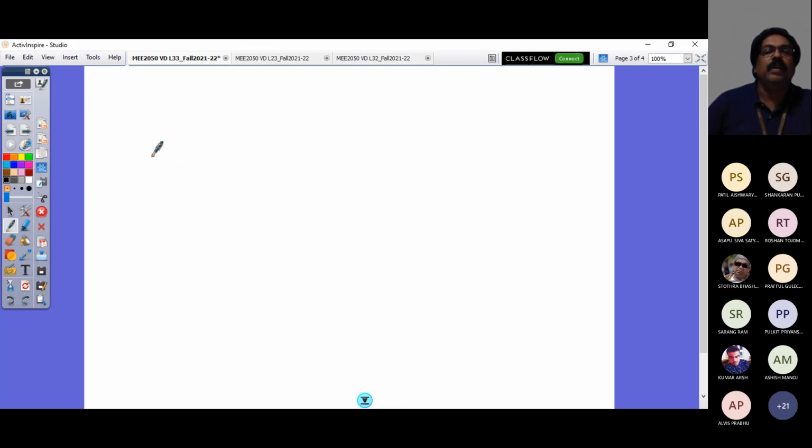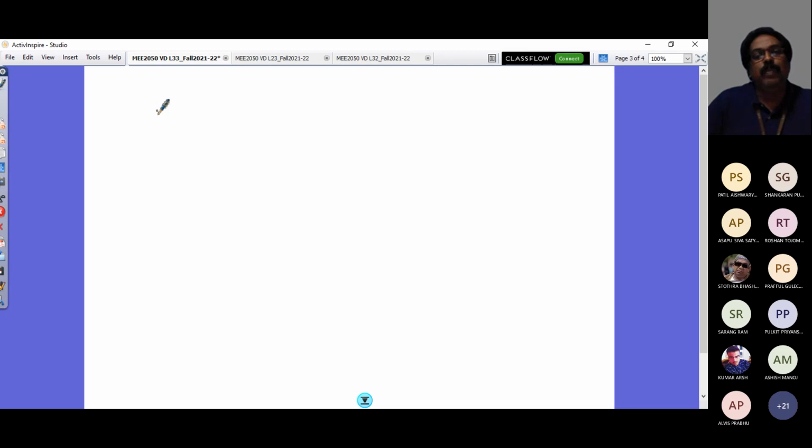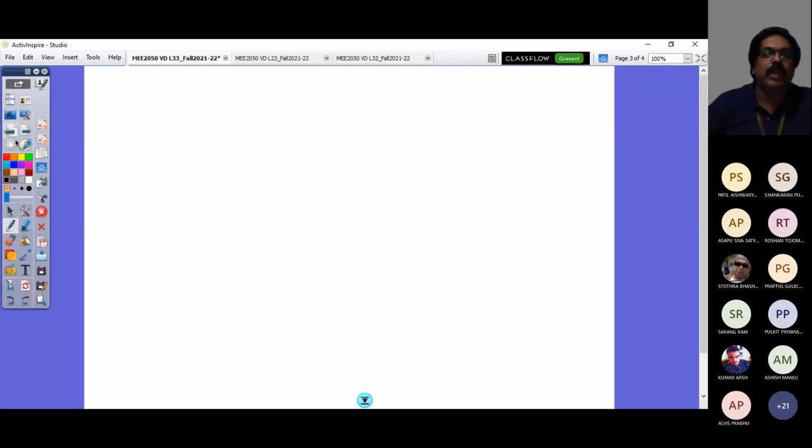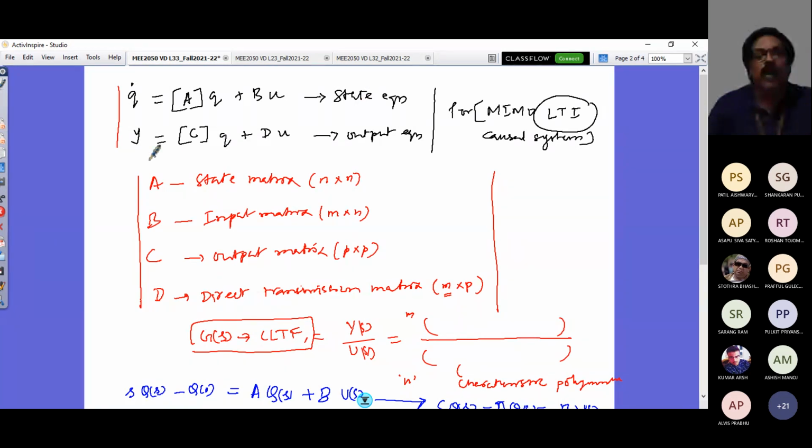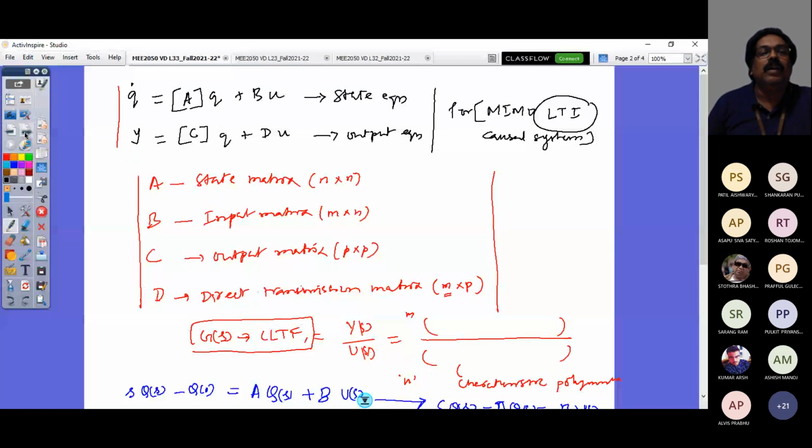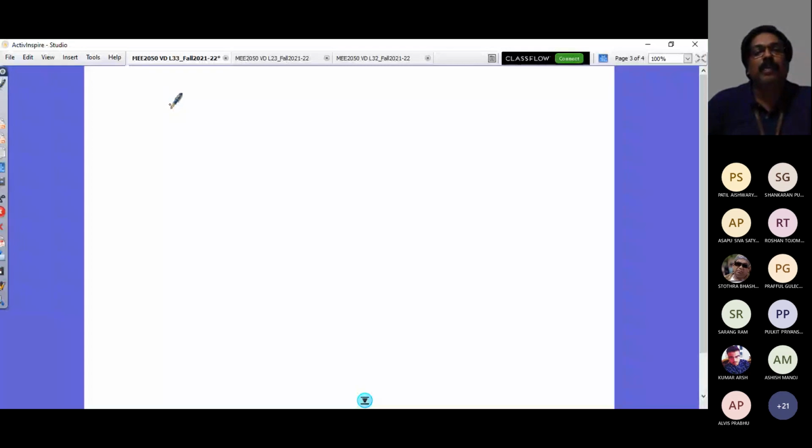What is that? It is the representation of the state space equations that we had as a control system block diagram. If you represent it as a block diagram, that helps you to design or look at parameters that are important explicitly in your system. So for that, let me draw a block diagram representation of the equations we have derived. These are the state equations. And how do I represent this state equation in a block diagram, so that you can connect the equations nicely to develop a block diagram that can be further reduced to a convenient form to design control strategies, right? So for that, let me write: block diagram of the linear continuous time control system.